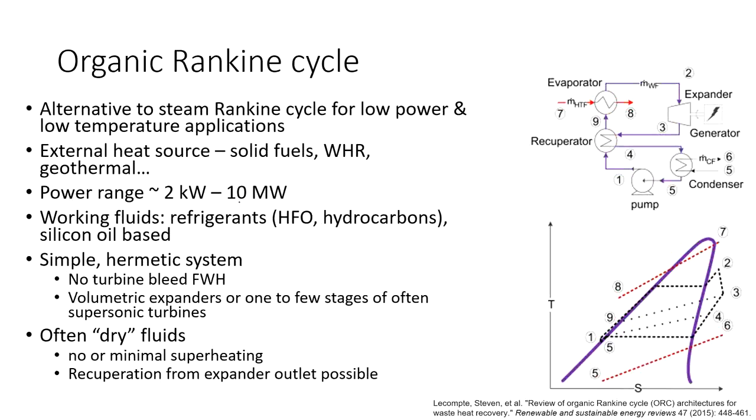As the name says, the working fluid is organic based. Typically there are used refrigerants like hydrofluorocarbons and hydrocarbons, working fluids that we have had in the last tutorial, or some, for example, silicon oil based fluids, as we will have calculation with one of them called hexamethyl-disiloxane.